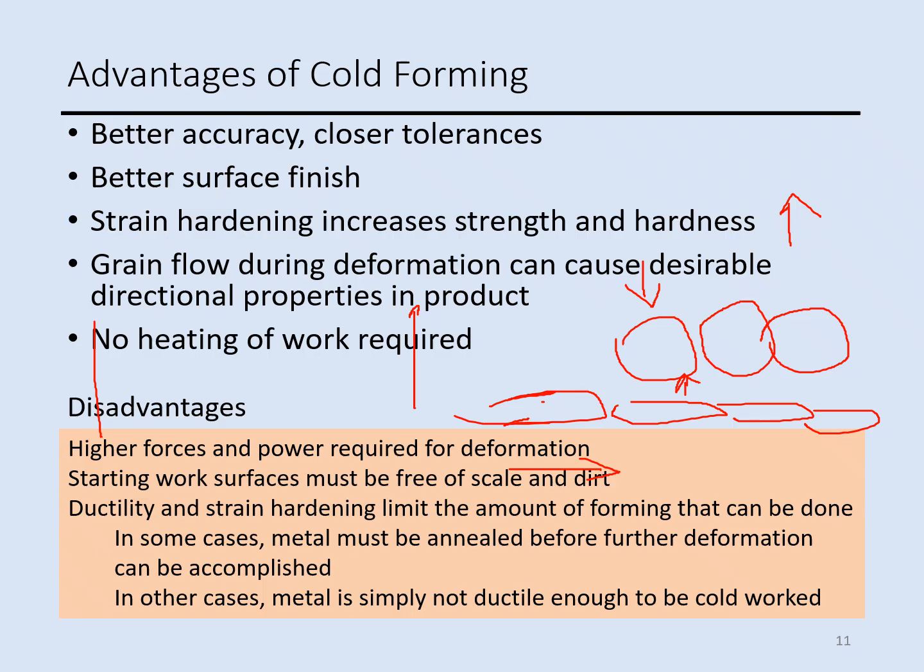It shouldn't have any oil, dust, or dirt on the part. And ductility is one thing that we have to consider in cold working, because some of the materials are not ductile, so we cannot apply too much stress in the process.